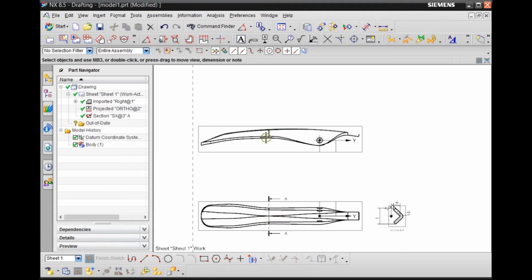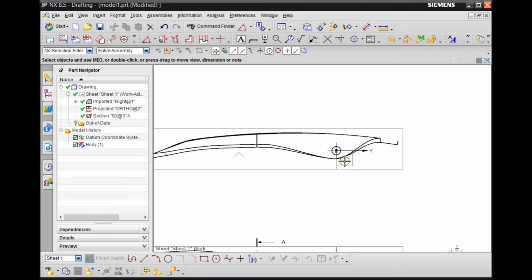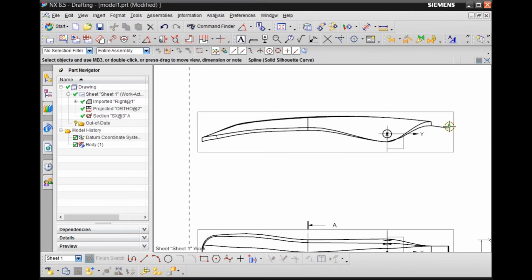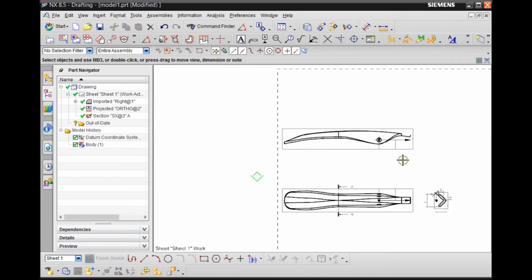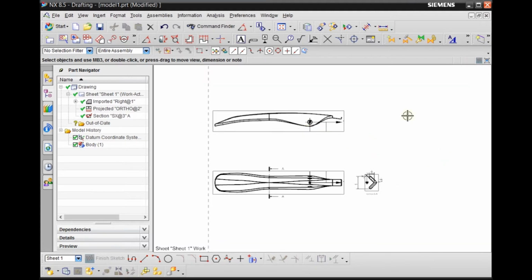This will indicate I created this model by swept, and that's one cross section. You need one at the origin, and that's another cross section, and that's the end cross section. So probably I have another one here. Now you can keep doing cuts and measure all the dimensions you need. And I'm going to talk about the swept command.